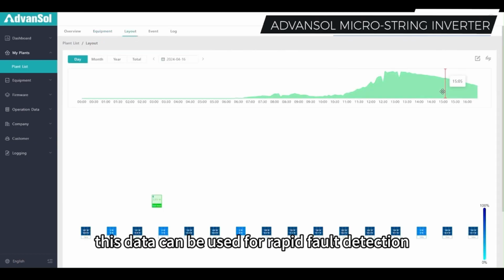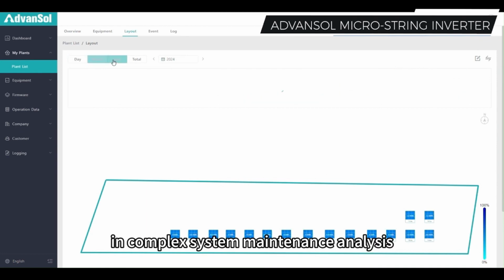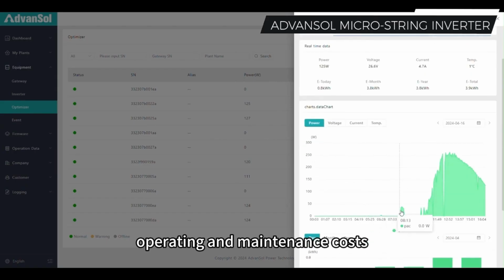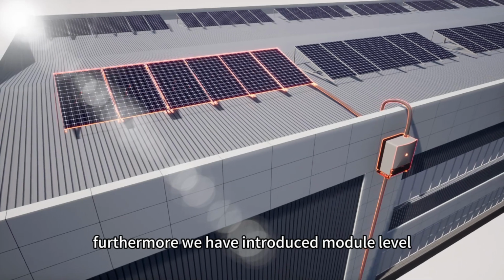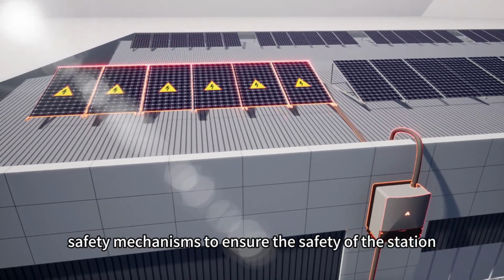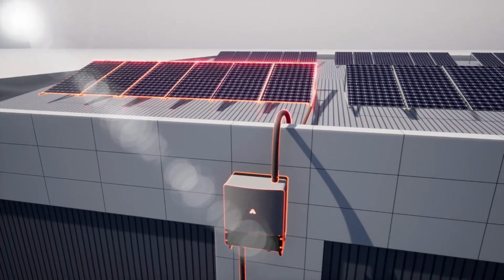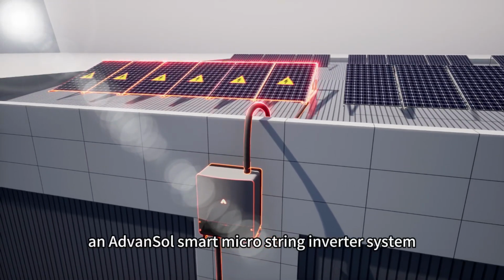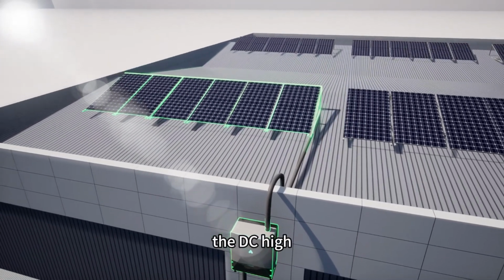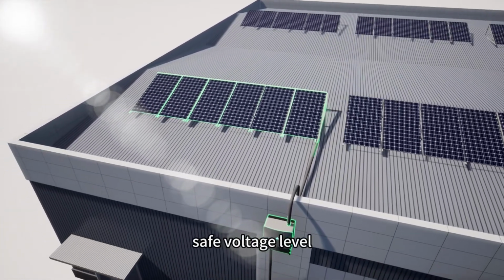This data can be used for rapid fault detection, real-time alerts, and complex system maintenance analysis, effectively reducing the system's operating and maintenance costs. Furthermore, we have introduced module-level safety mechanisms to ensure the safety of the station users, installation workers, and firefighting personnel. In AdvanSol Smart Microstring Inverter system, when the AC power is disconnected, the DC high voltage of the strings is automatically reduced to a safe voltage level.